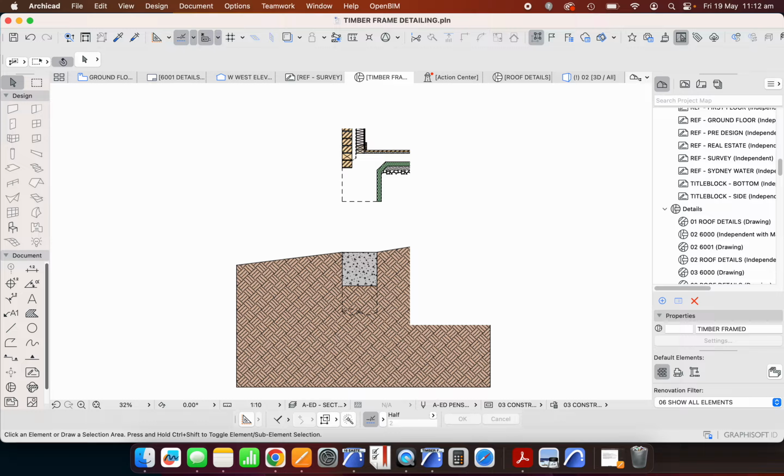We also are going to have a continuous subfloor wall, and so therefore there is going to be a bit of load placed on it, and we don't want any movement. It's not just an isolated pier. This is a continuous strip footing, just for clarification. Now, this also means that we've got our bricks running all the way down. We may still want to have our weep hole up here, and then we're just going to copy these bricks down as we did before. So that'll be multiplied by 86 millimeters, and we can just copy those all the way down.